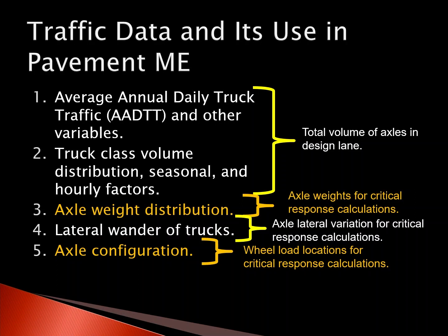And as you will remember in Module 2, the Pavement ME Design software uses load superposition for flexible pavement design for calculating the responses under as well as between different axle loads and axle load locations using elastic layer theory.